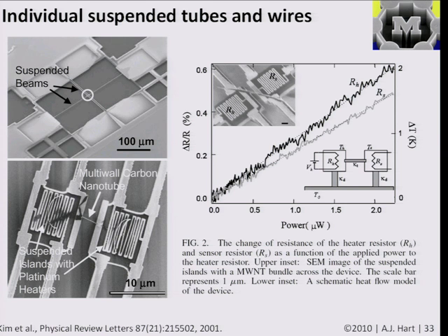And what we know is for platinum, the resistance is proportional to its temperature, the electrical resistance. And we also know that from Joule heating, if you pass a current through, the wire will heat up. It dissipates power as I squared R. So as you send current through here, this wire is going to heat up, and its resistance will change, and it will also dissipate a power that you know. And there's a little bridge connecting this to this, and that's the structure you're going to measure.